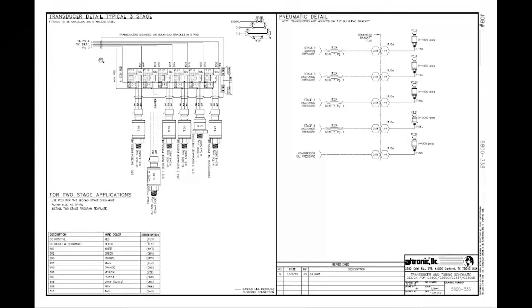We show how we have a 5-volt supply coming in, and it's kind of hard to see. It's going to be hard for me, the way I'm sharing my screen, to zoom in and out. But we do show a small little tiny connection of this 5-volt wire as it comes across being jumpered into every terminal block. The same thing with our A common and black wire, goes across and does the same thing.